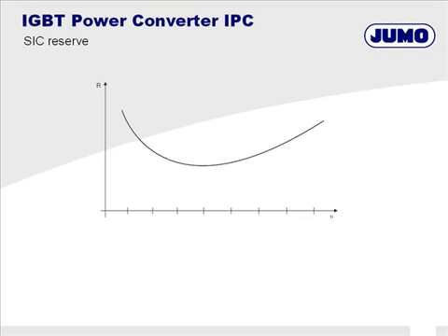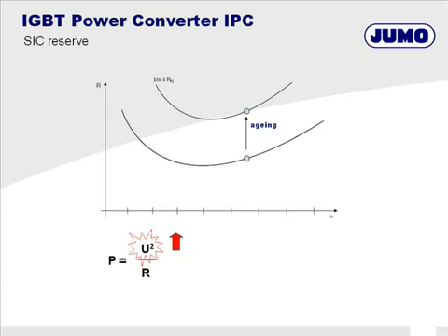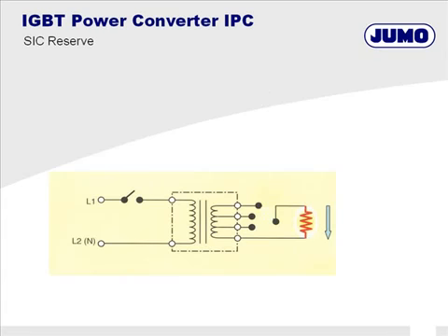The resistance of SiC elements rises during the running life. Consequently, when the voltage remains stable, the power and the temperature of the heaters are reduced. You have to increase the load voltage to generate the same power. To increase the power, you have to use a transformer with several voltage tappers for the thyristor unit.